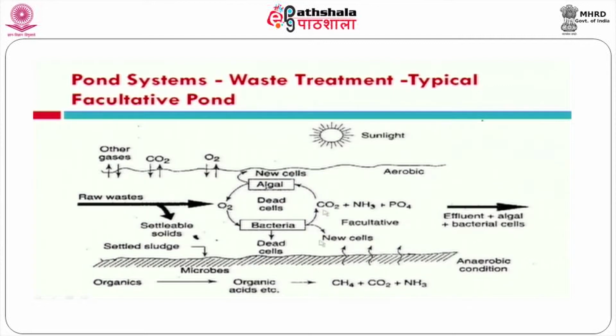But if you investigate the DO level with respect to the vertical direction, the DO level at the top surface of the system will be high during daytime. Gradually it decreases with respect to depth because most of the algal species are present on the top surface of the reactor. If you want to keep your reactor in aerobic condition, the minimum depth to keep aerobic activity is up to 0.9 meter, sometimes it can be extended up to 1.1 meter. If you operate your aerobic pond at low loading and the depth is shallow, aerobic bacteria are predominant in our biological system.